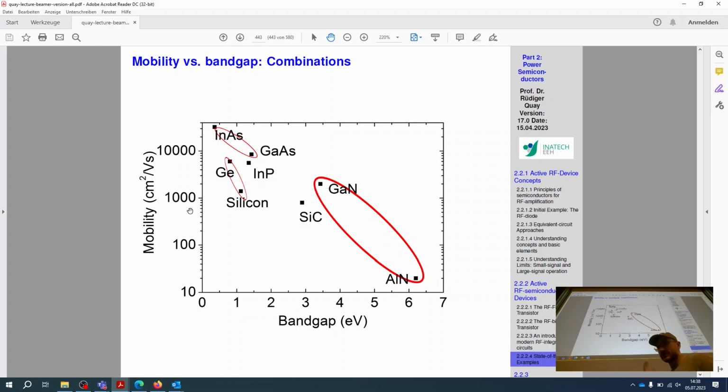Gallium arsenide is also a high band gap material, usually above 1.4 electron volts required to move from the valence to the conduction band. That is called a relatively high band gap semiconductor, and an initial example of that was gallium arsenide. Gallium arsenide has been in use since the 60s, and maybe even beforehand, intensively in the RF world. Nowadays you can reach operating frequencies in Fmax and FT.